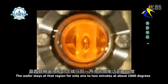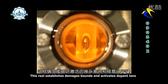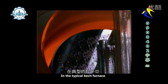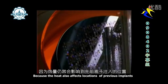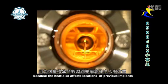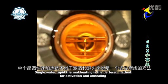The wafer stays in that region for only 1 to 2 minutes at about 1000 degrees. This reestablishes damaged bonds and activates dopant ions. In a typical batch furnace, this process requires 20 to 30 minutes at high temperature. Because this heat also affects the location of previous implants, single wafer rapid thermal heating is the preferred method for activation and annealing.